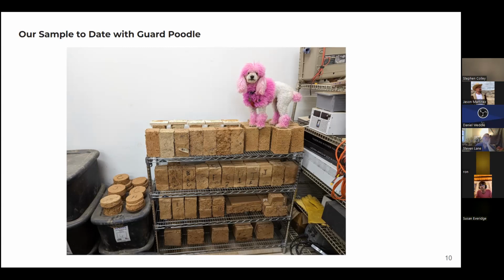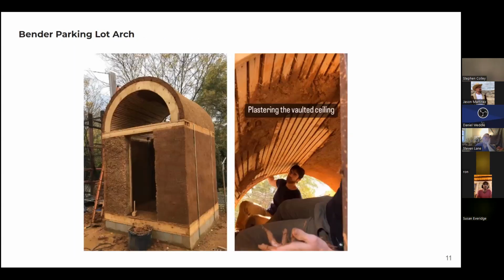And we did get a high enough R value in our most recent testing round to be deployed in a performance review, at least to our climate and probably 1 or 2 zones above. And we can pull the structural steel out of the system up to seismic category C. So we are making big movements in a deployable monolithic system.